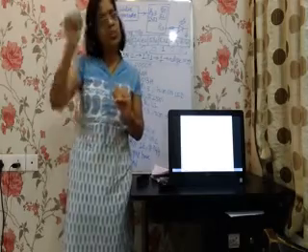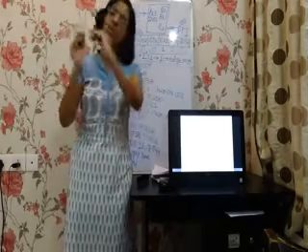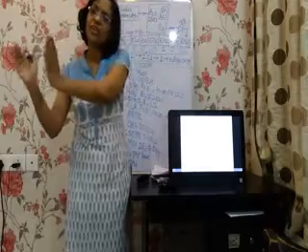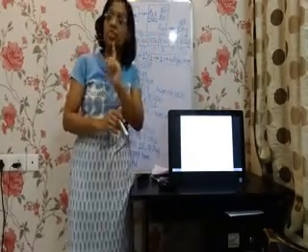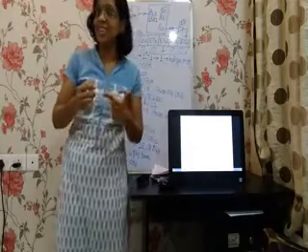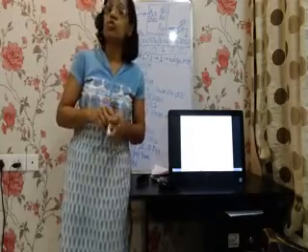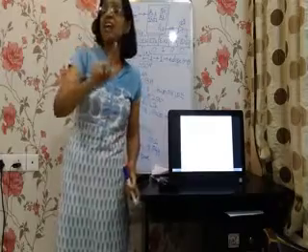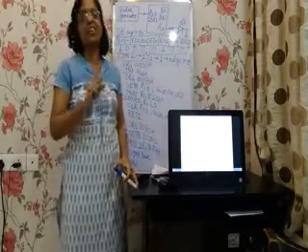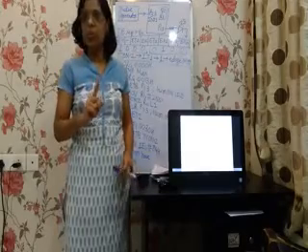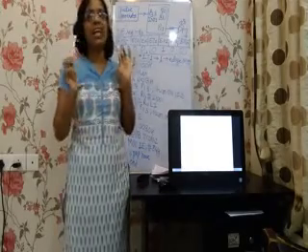Upon execution of RETI, what happens? The control goes from the interrupt service subroutine to the main program again. But in addition to popping out the PC contents, RETI also does one more thing. It makes IE0 and IE1 equal to 0. So this is the main difference between RETI and RET.